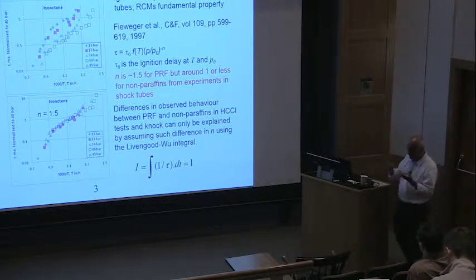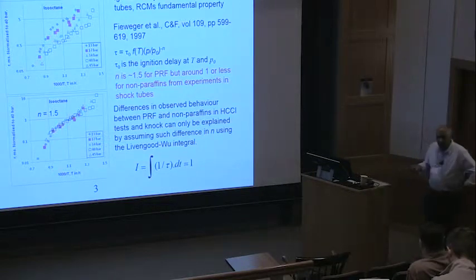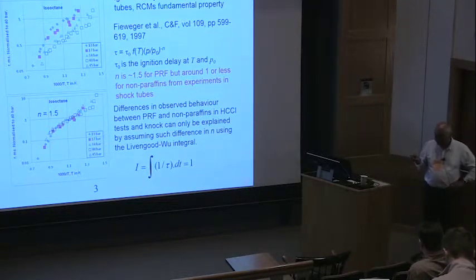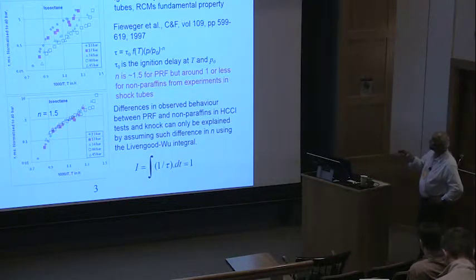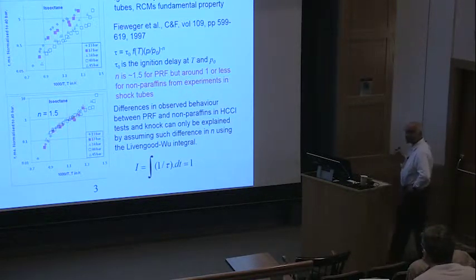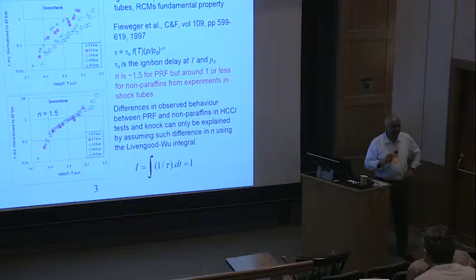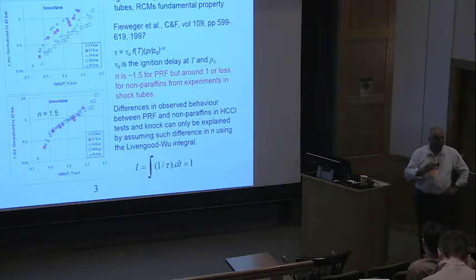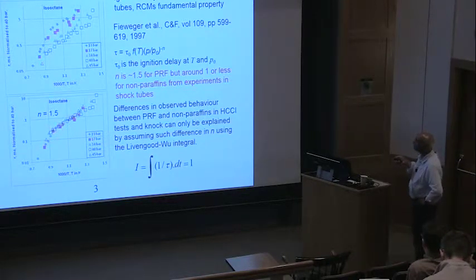But still, that allows us to make informed judgments. Now, I want to relate what we talked about earlier to more fundamental matters, that is to do with ignition delay. What you have to remember is ignition delay and auto ignition depend both on pressure as well as on temperature. Quite often in chemical kinetics, of course people know that it depends on pressure, but the focus is always on temperature, when we talk about the NTC region and so on.